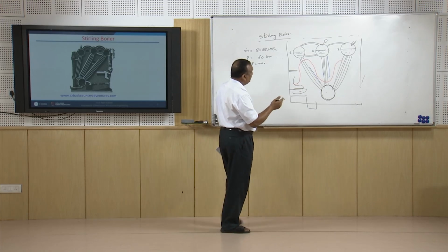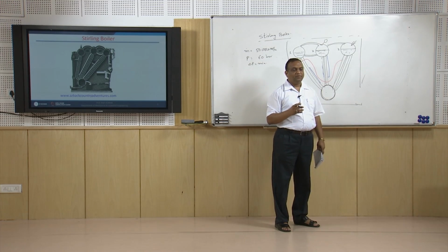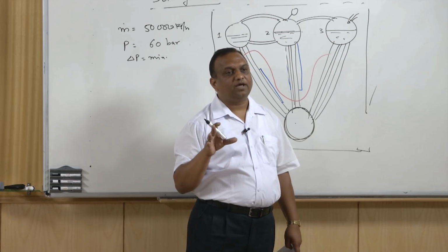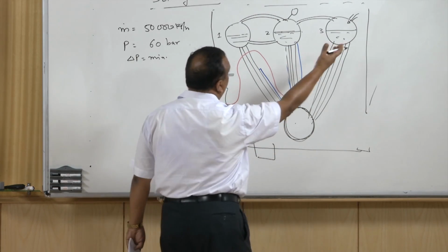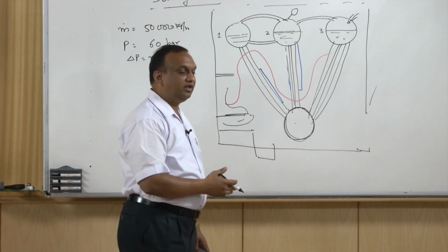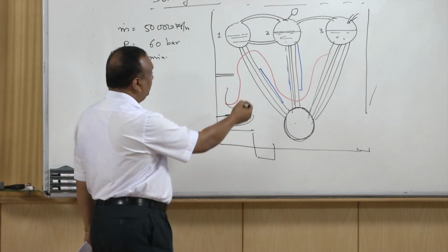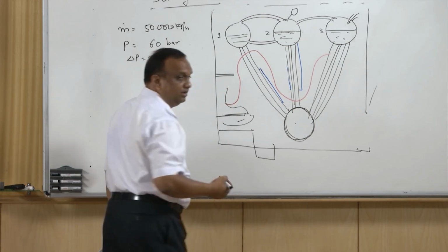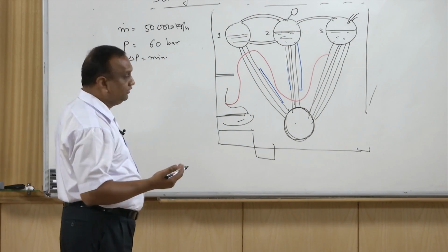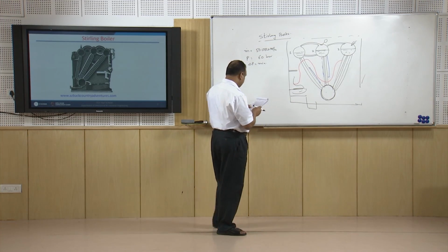And this boiler permits a great flexibility in the design. I mean, as per your requirement, you can change the design of the boiler. You can go for, say, a 6 drum boiler and you can add here 3 more drums, right? Tubes, they are bent tubes. Because they are bent tubes, that is why no thermal stresses are developed inside the tube. That is the benefit of this tube.